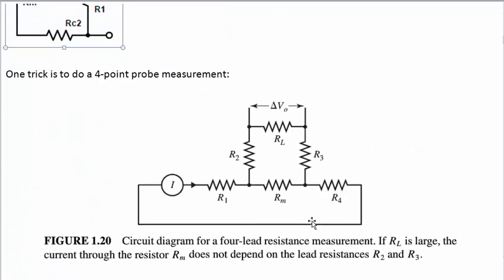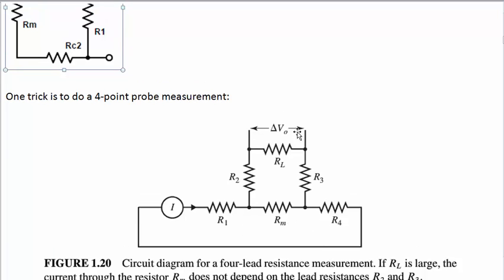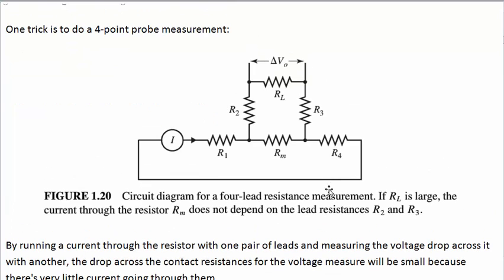We have a setup to do this over in the tandem accelerator building. So if you go over there, if you've worked in the summer, then you can ask Sharam where the 4-point probe sensor is, and it's set up so that you measure the voltage and you measure the current and use that to figure out what the resistance is, using an equation that you can go and derive with all the math that you know right now.